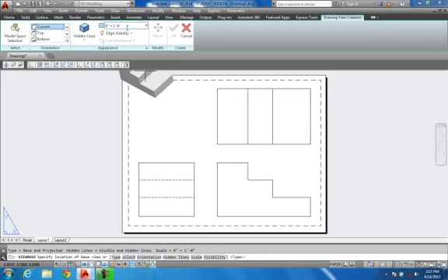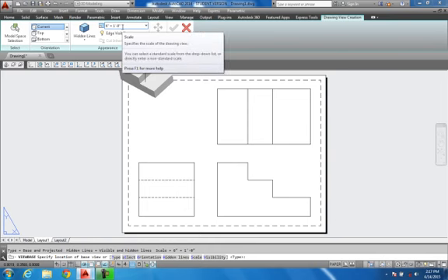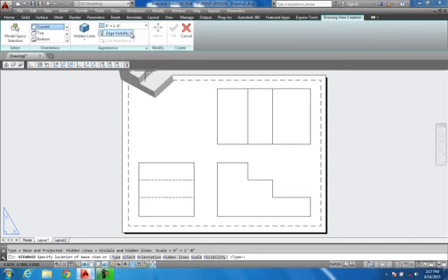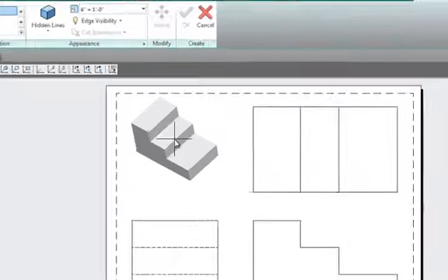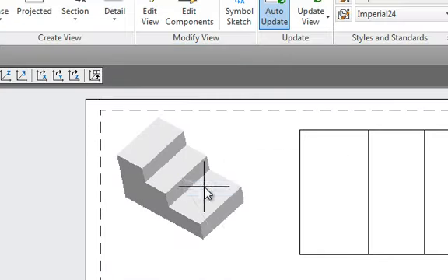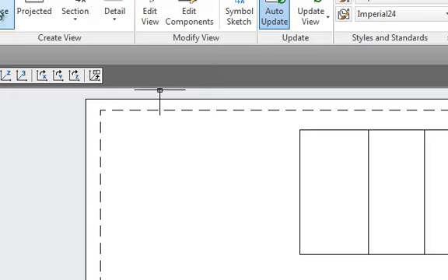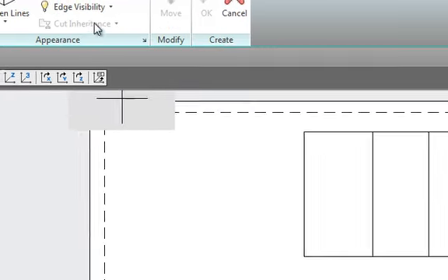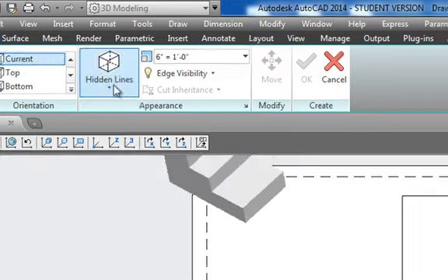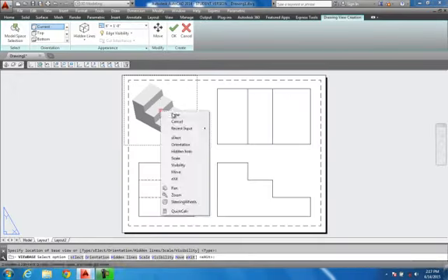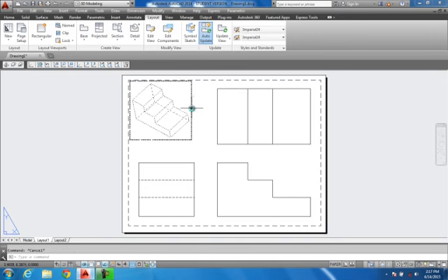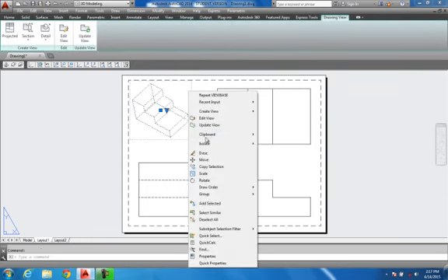And if this scale's not what you want, if you want to use just regular scales like 1:1, 1:2, 1:3, 1:4, or 2:1, something like that, you have to add them in your model space by customizing. But anyways, you click right there, enter, and you've got yourself an isometric view here, or a 3D view. It's just a little bit off isometric.